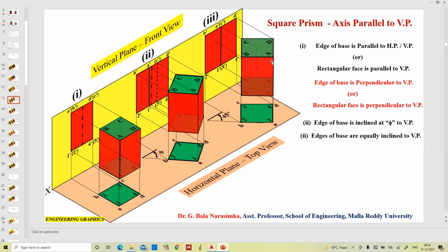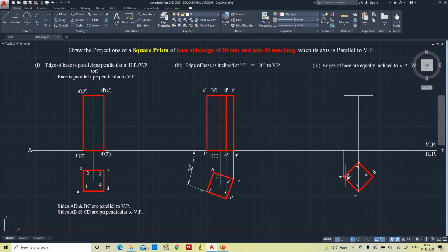As of now, the first priority wise we are going to give to the continuous line, so that's why represented with continuous line. The same you can see here also, visible line, center line, continuous line. So first priority visible line, in that case everything will be continuous, there is no center line and hidden line in this thing.